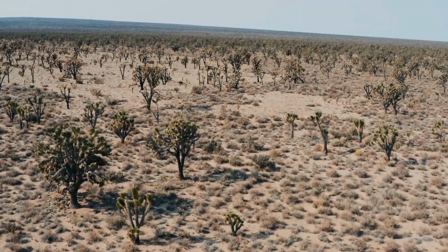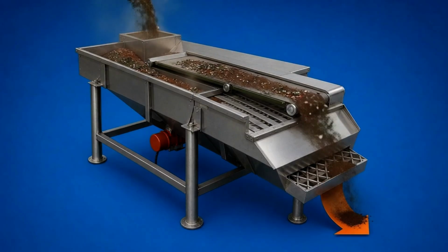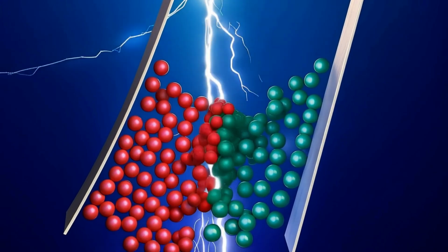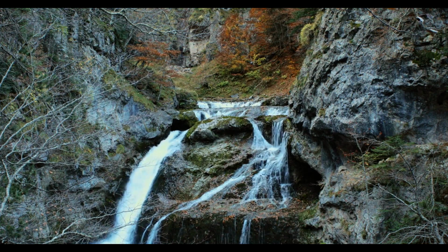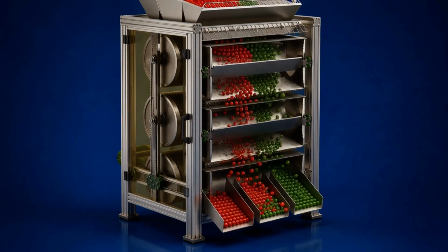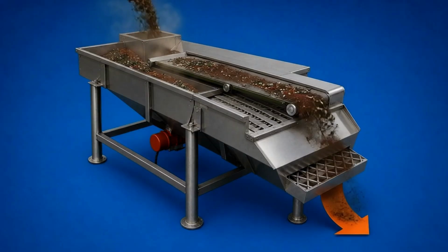In some cases, especially in arid environments, dry concentration methods are preferred. These include electrostatic separation and dry washer systems. The advantage of dry processing is that it does not require water, reducing operational costs and environmental impact. However, dry methods are generally less effective for very fine particles, and can be sensitive to environmental factors such as humidity. To address these limitations, Avametal has developed a combined system that integrates electrostatic separation with dry washing.